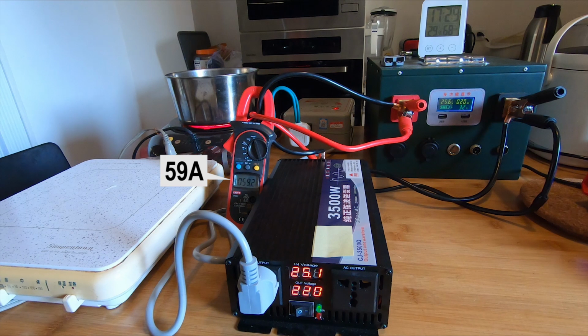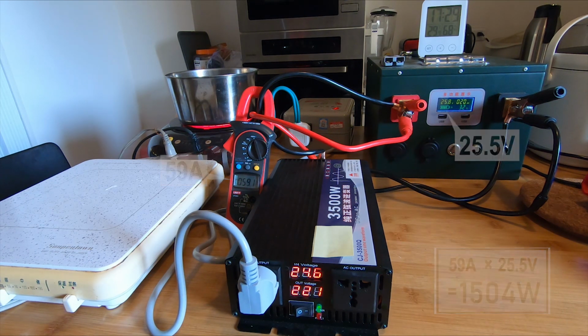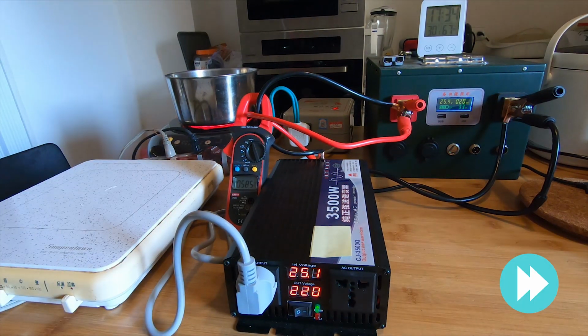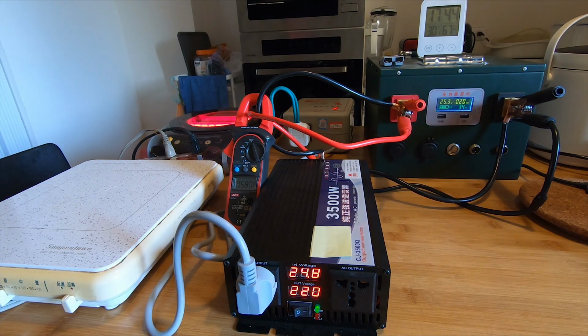The DC current output on the current meter is about 59 amp. The battery voltage is 25.5 volt. At this time, the power output to the inverter is about 1504 watt. After 15 minutes, the water is boiled, and then replaced with 800 cubic centimeters of water.